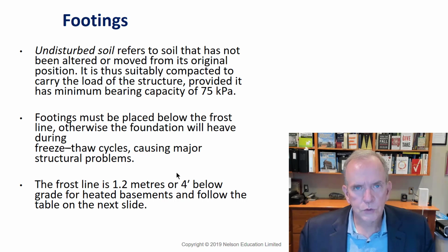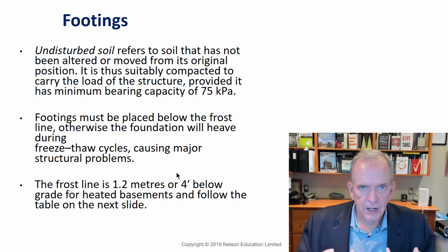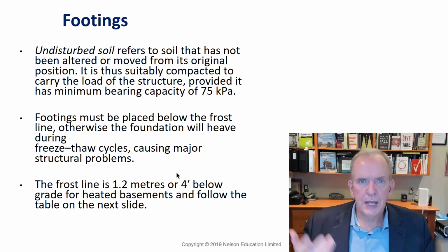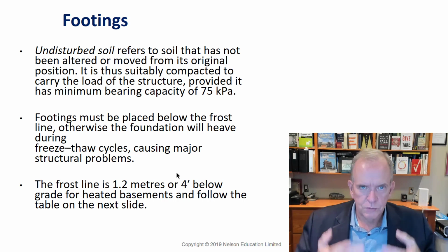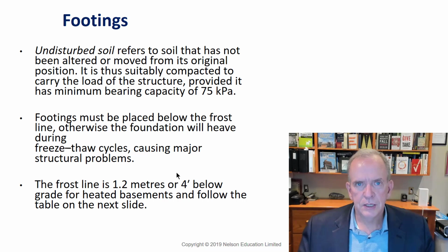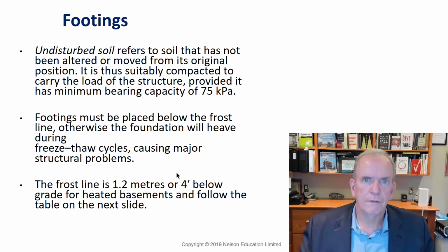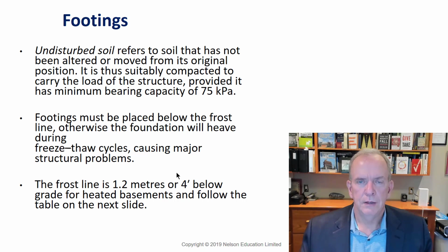Now you probably wouldn't notice what it heaves up in a year. It probably heaves it up a quarter of an inch, and maybe in the spring it goes down an eighth. Some soil fills in underneath it, so it doesn't go all the way down. Then the next year it goes up another quarter of an inch, and it goes back down an eighth. After about a dozen years, the fence might be 3 or 4 inches up or pushed off to the side because it didn't go down the full depth of 4 feet. Somebody took a shortcut. Same thing would happen with a house or a building.